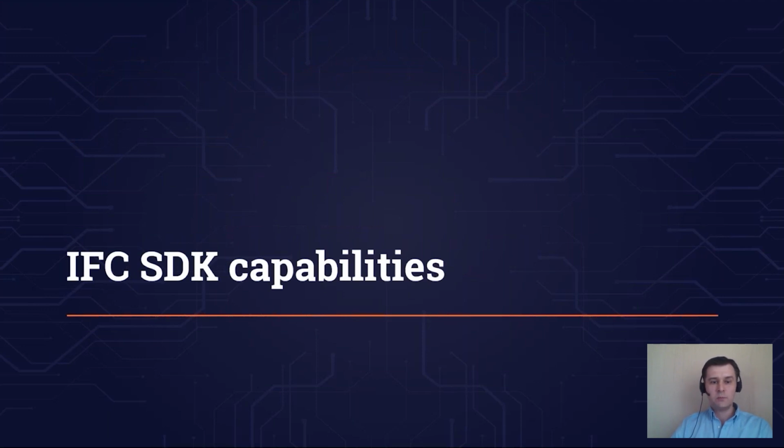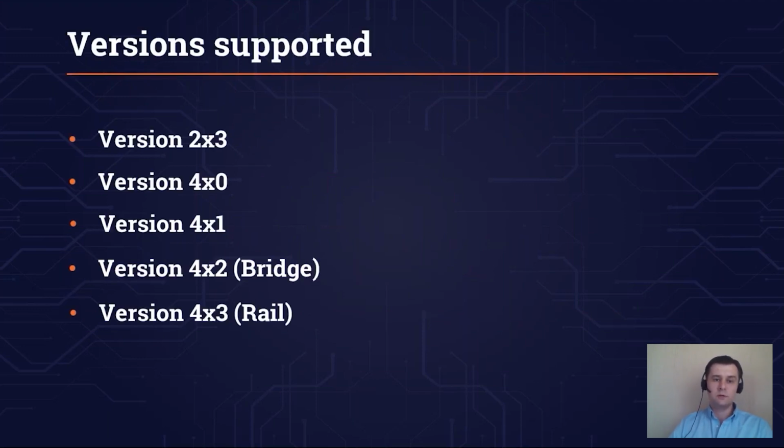And as for our capabilities, the result of our efforts and of partnership with Building Smart is the following: we support versions 2x3, 4x0, 4x1, 4x2, and even the candidate standard 4x3 that was announced and released in April this year, 2020. We already also provide access to the data stored in this format, and we'll need some time to provide full support of this version.